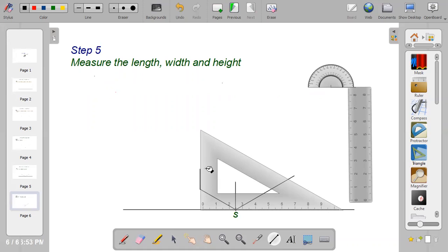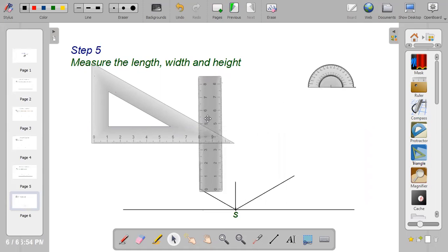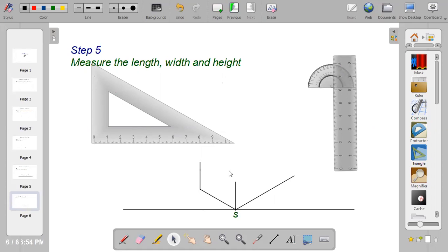So now when you measure 20, you place your ruler to be sure it's equal to 20. I'll remove my set square, place my ruler on the line to be sure I have 20 mm. Very correct. So I have 20 mm now. Like in my other video, I told you that when you have two equal lengths, you join them together with a straight line. So I have 20 plus 20. All I need to do is to join it together with a straight line.